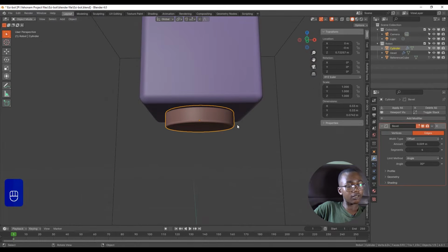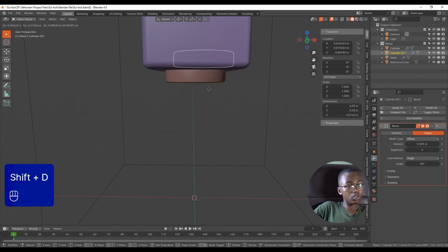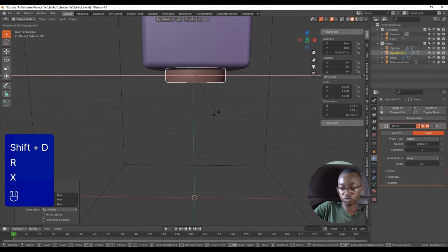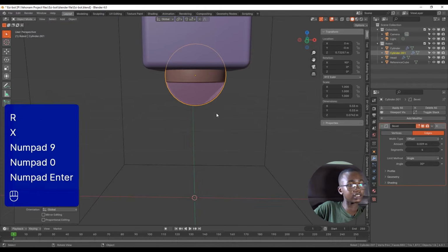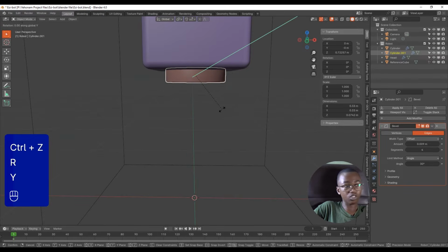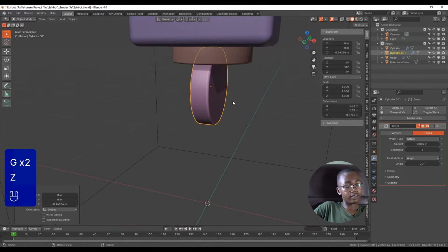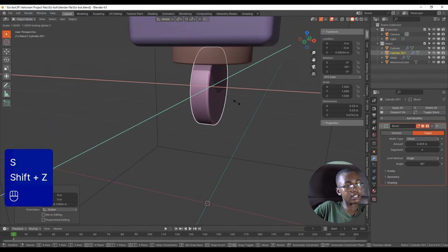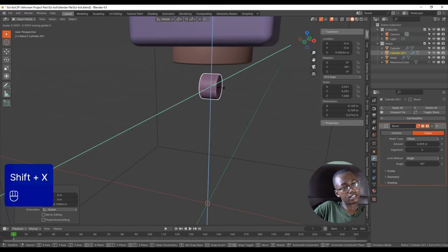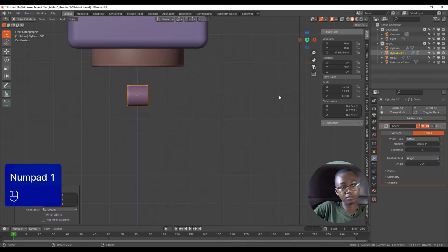Yeah, so you can start from that. See that, then you can also duplicate that, rotate it on the Y axis 90 degrees, bring that down, press S, Shift Z or Shift X, yes, to scale it on all the axes but the X axis, so you get that nice and uniform scaling over there.